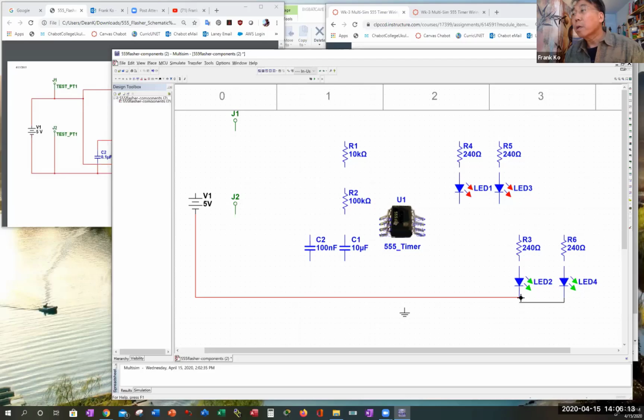Click. I have to make a click. Click, and there should be a dot. Click. Is there going to be a dot here, or is it going to click over here? Okay. If it doesn't click at the bottom of the component, make sure there's a node that somehow attaches near the component. This ground wire, click on here and bring it up to the wire and click, and it will create a wire connection there.